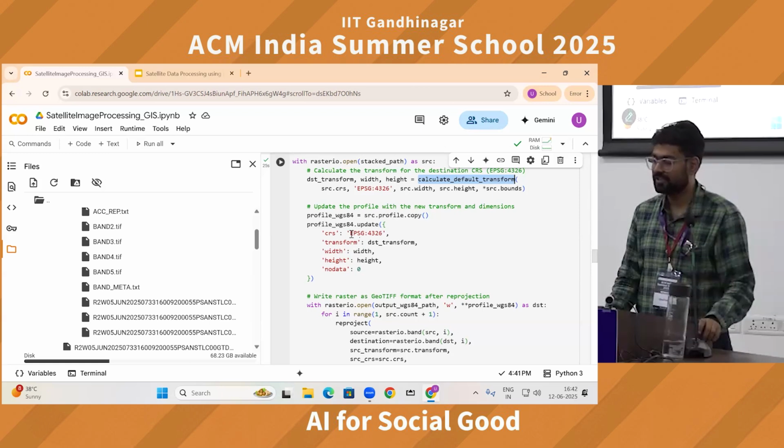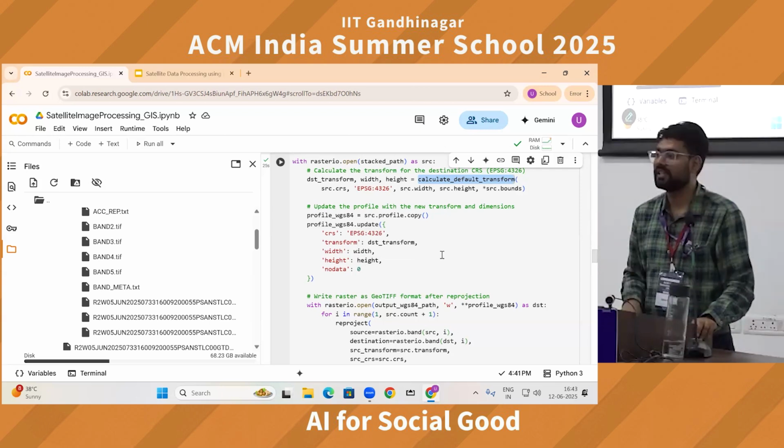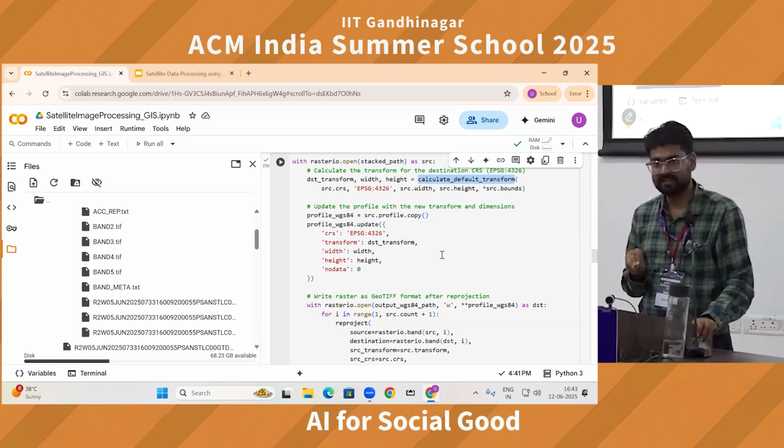For example, we changed our coordinate system, which is now EPSG 4326. Transform information we have changed, so that information is given here. Width and height is given here. Here I have changed the no data value, because in the earlier image, the no data was not given. But here I explicitly mention it. Okay, whatever pixel has the value 0, please do not consider as a valid pixel.